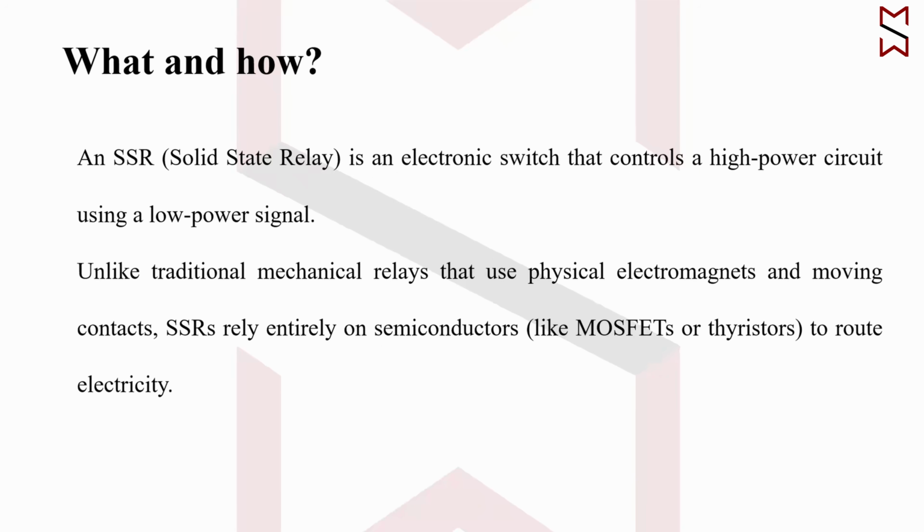An SSR is an electronic switch that controls a high-power circuit using a low-power signal, but that can be done using traditional mechanical relays also, that use physical electromagnets and moving contacts. But SSRs rely entirely on semiconductor switches such as MOSFETs and thyristors to pass electricity.